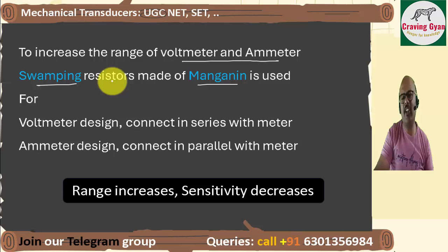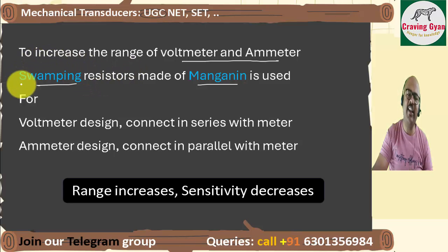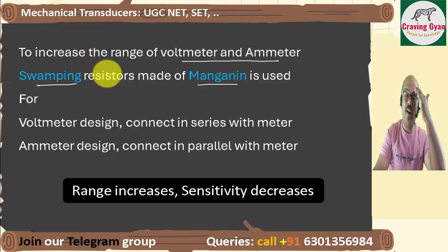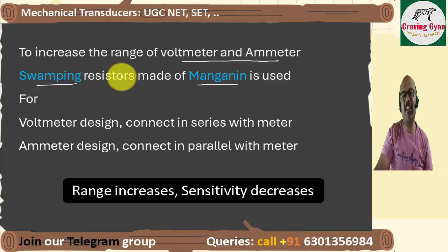Usually, like 5 years down the line, you just refer to the previous year question papers. They were asking these kinds of questions: what was the resistance made up of, and what resistance are we going to use. Simple thing, in the case of a voltmeter, one extra resistor you connect in series will act like an external resistance, thereby the voltmeter range will be increased.